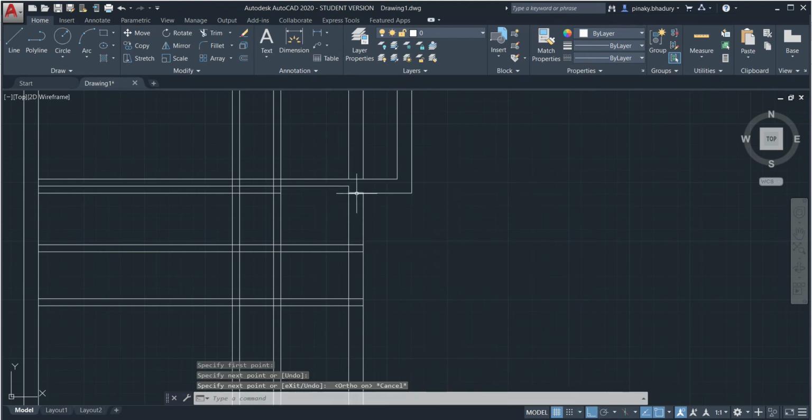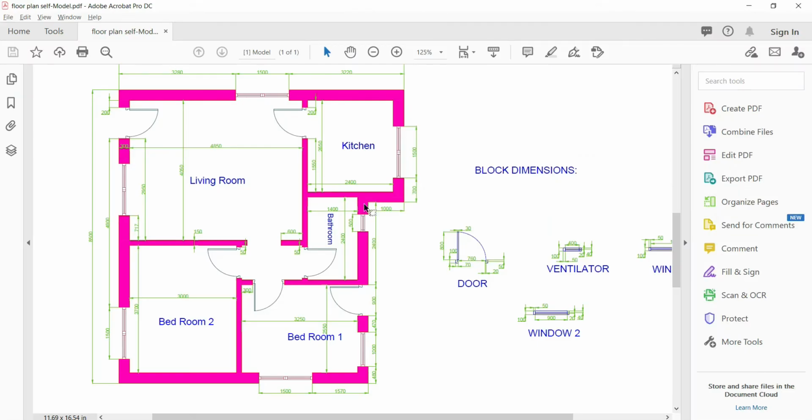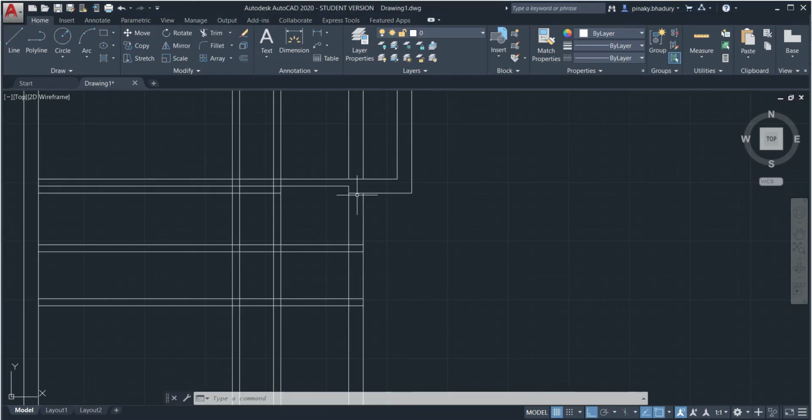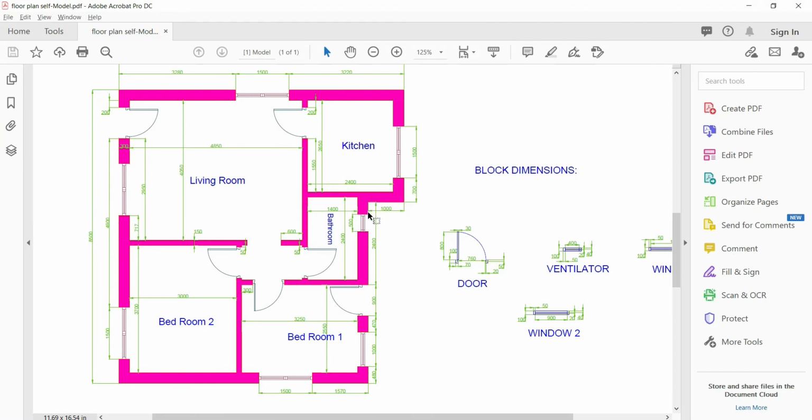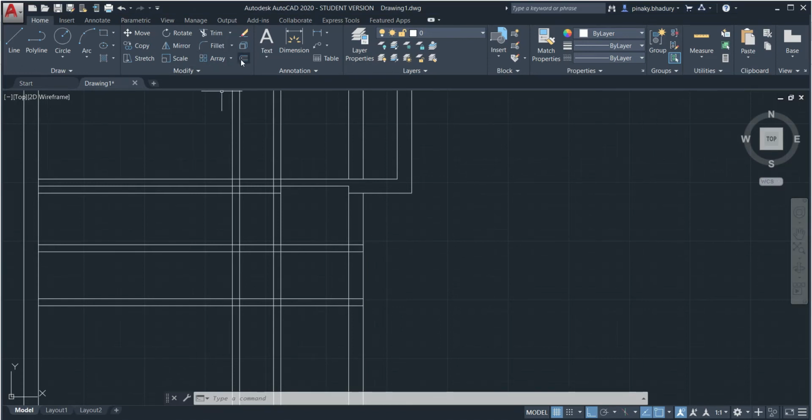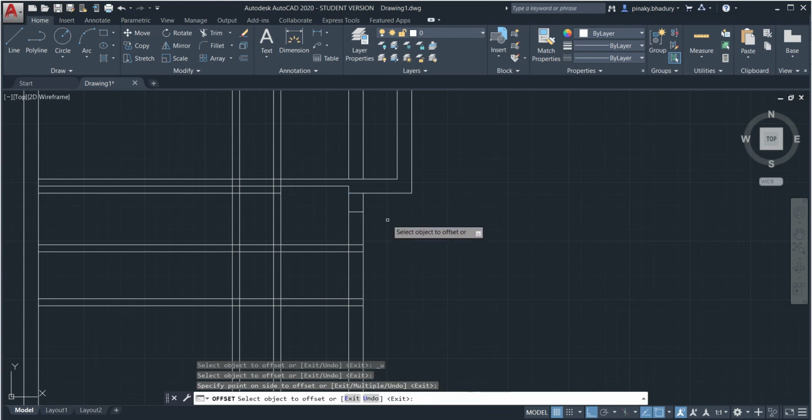So this is a small line that I have created, and I will bring this at how much height I have created the line here. So I will bring this down to a height of, this is 600, that means this is 150, that means 450 I will take. Okay, so I will use the offset option, give the distance as 400, click on enter, select this line, bring it down at 400 distance, right? Similarly, and now I can delete this line because I don't require this.